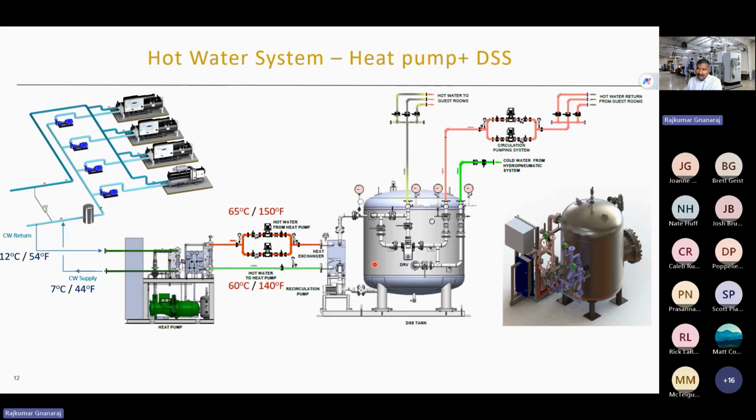So Hilton and Marriott standardize this kind of design to keep the hot water at 140 degrees Fahrenheit or above, because it's stored in a tank so that the Legionella bacteria gets killed within a few minutes. So this is a typical installation for a heat pump to heat domestic hot water.